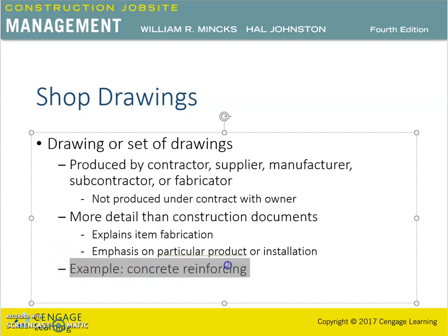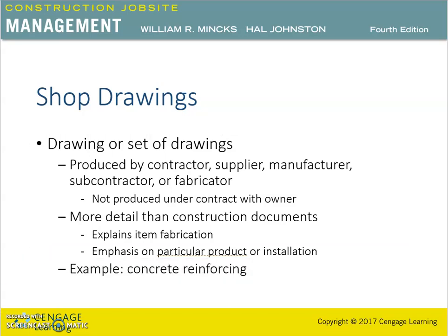As an example, concrete reinforcing is one of the primary items requiring specialized shop drawings for the fabrication of the materials. The reinforcing bars are cut to length and bent to specific configurations. The shop drawing and the accompanying cut sheet list the quantity, sizes, lengths, and shapes of the reinforcing bar. Each supplier or manufacturer will have specific information that should be included on shop drawings.